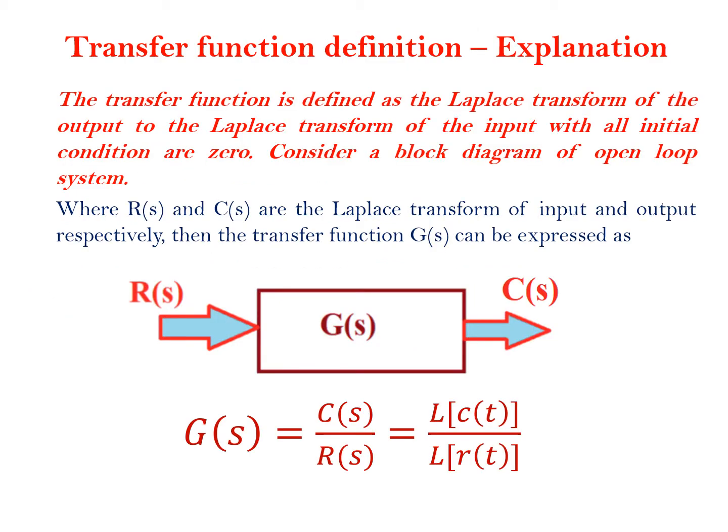First of all, I am going to explain the definition of the transfer function and then I'll give the explanation of the transfer function. What is the definition of the transfer function? The transfer function is defined as the Laplace transform of the output to the Laplace transform of the input with all initial conditions are considered as zero.